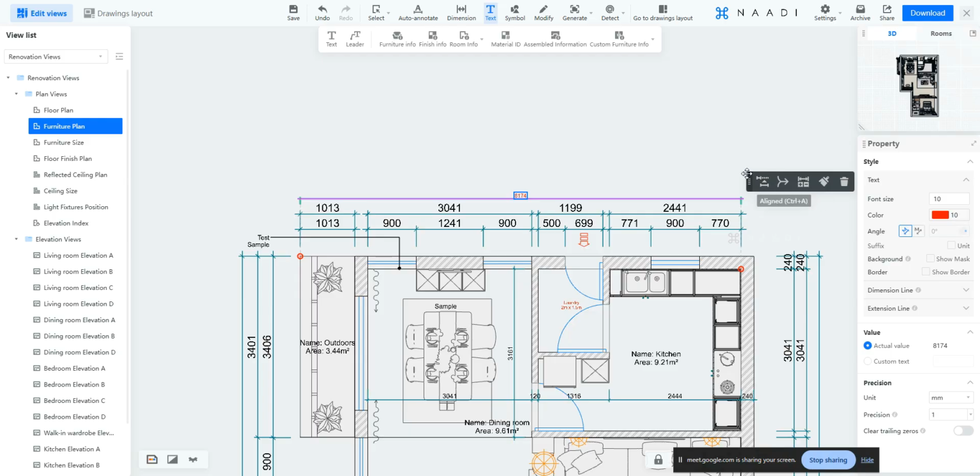Always remember, this floating window will have some important tools to edit that selected component, whether it is modeling, 2D, anything. If you're seeing this floating window, it will always carry some important tools which will help you to edit that selected component. So in that way, one of the tools here is your format painter. Can you see? Shortcut is here. Click it. Now this format is copied.